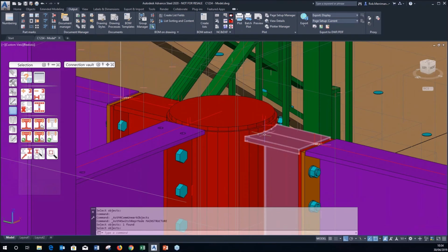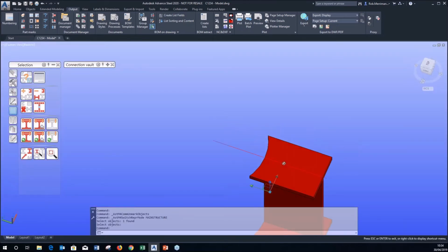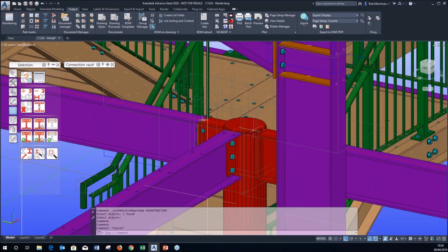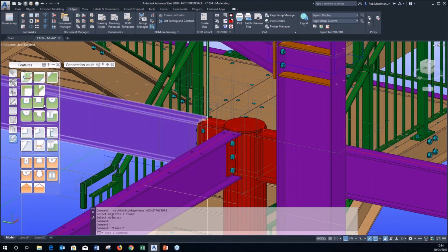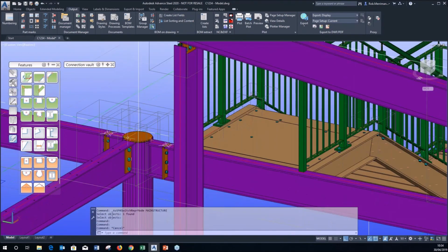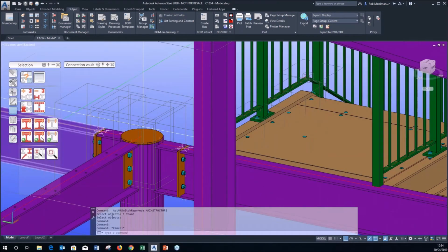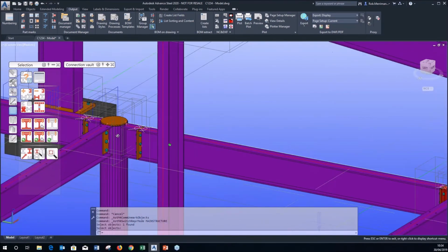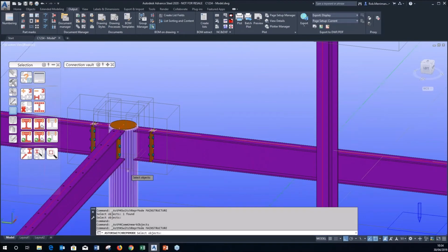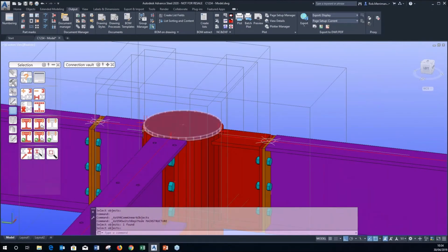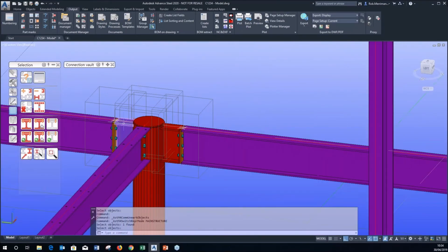The items that I've manually put in is the contour on this stub, because it's curved to suit the column, and then you can turn the weld on or off in there. So I think it'll be element contour rule to cut that. So because I've done that manually, I would double check each one of these columns, as I have put a deliberate mistake in here. If I choose this column, we can see that this side has not gone red.